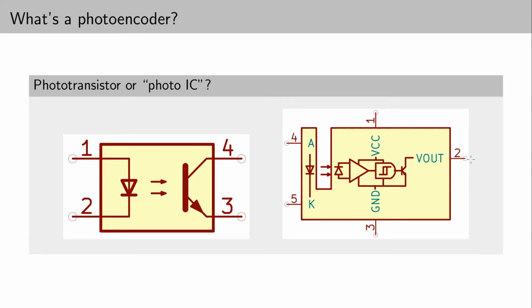So in the usual way with these things, you put a pull-up resistor here, and then the voltage at this node will alternate between ground and the power supply, depending on whether this transistor is switched on or off by the Schmitt trigger output here. And so all of the processing of the analog signal from the detector is managed for you.